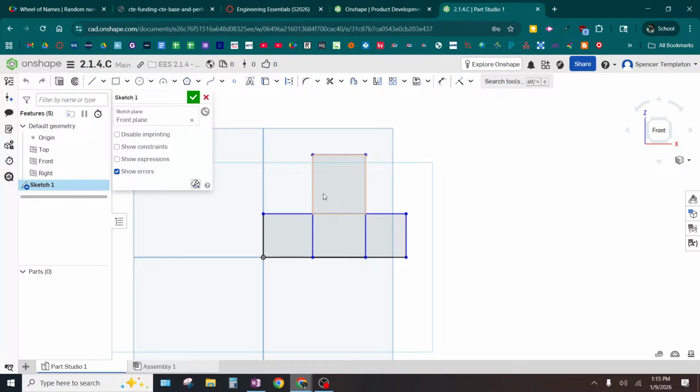Opposite sides are parallel. Every corner is a 90-degree angle. If I use the line tool and accidentally mess up while drawing it, I might misapply a constraint. There's more likely for errors or issues. I don't mind selecting 4 things to extrude. I'd rather have more reliability in the sketch. But that's just a personal preference. I don't care what you do.